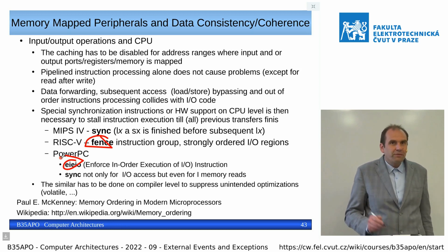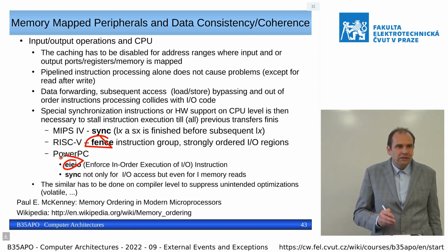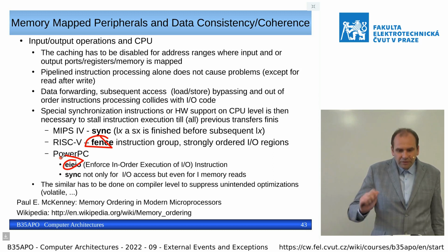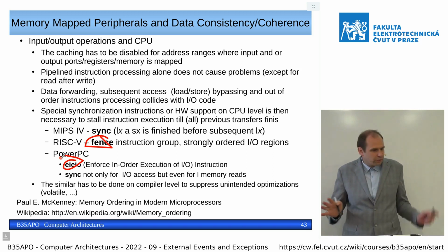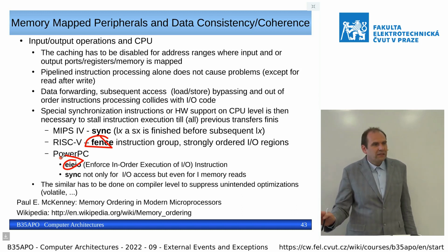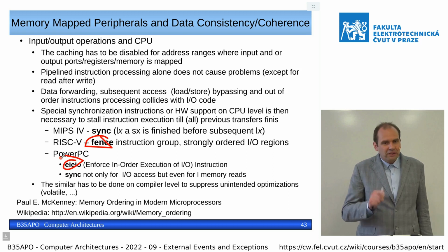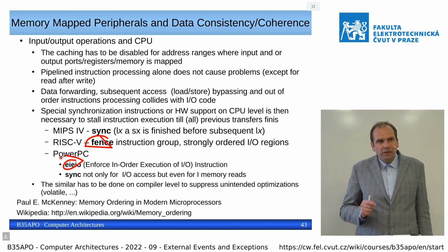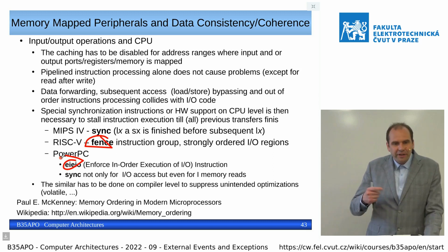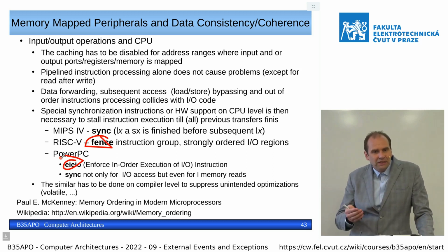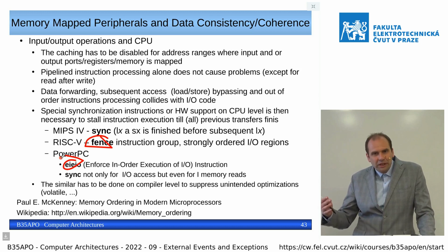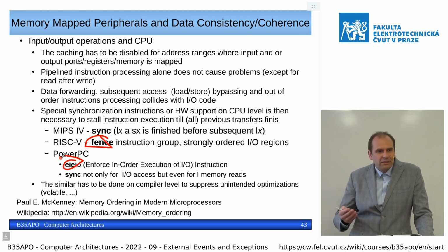So even if you put a volatile modifier on the actual access, you can get to the state that the actual data has not been delivered to the port which controls the LED. I have written the code, it was correctly written, ran it, and the LED didn't blink. And when I used the debugger, I saw that the processor is executing the code. The processor kept the written data in the write-back buffer, and because it doesn't need to write to any other location, it was simple code, the change was stuck inside the CPU and never appeared on the external bus and on the peripheral.